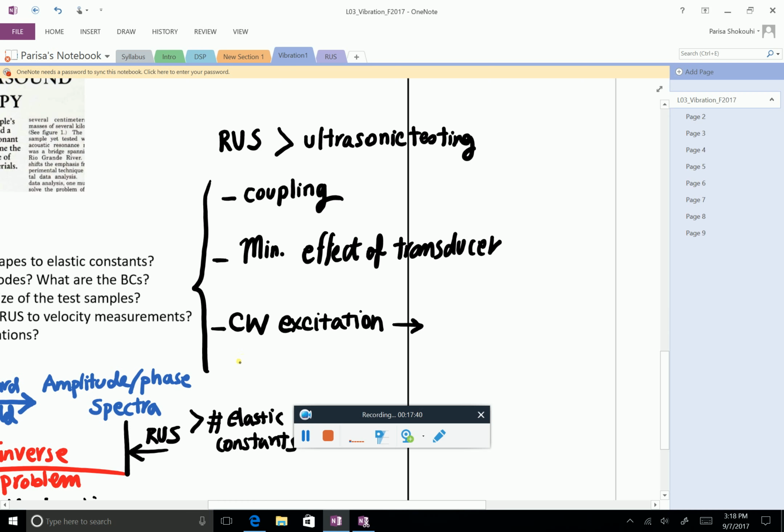This may not mean so much to you, but if you have very low signal to noise ratios, it's hard to see the arrival of waves when you measure velocity. But when you have a continuous wave, it's easier to just compare and look at the phase information to get the velocity or any changes from the phase of the continuous wave, because you can very easily reconstruct it. You know what frequency it is. So that's a kind of subtle thing.